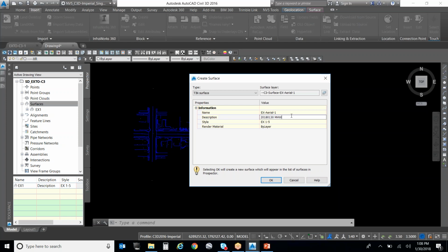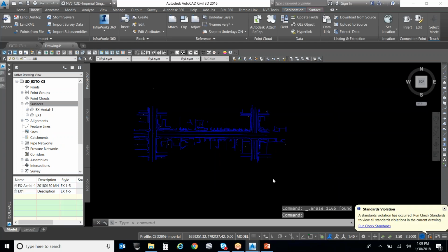It's one of the blessings and curses of having it preset to Zone 6 that a lot of times we neglect to check that. So if your project is in a different zone, be sure to do that through the Settings tab. The other thing available in the settings is all your Civil 3D styles. Basically, you don't really have any reason to go in there and edit them. Hopefully the template has enough styles for you so you don't have to edit styles, but that's where you would.